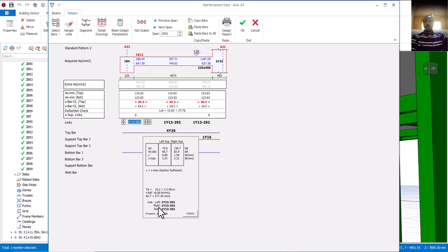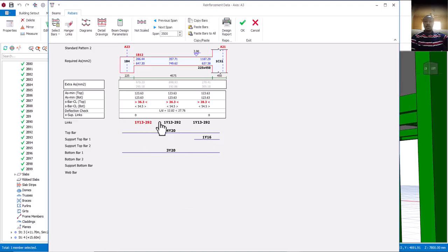So if this one has passed, at times why you see that red is because of this place. Understand? And this place talks about torsion. Many times why we see your link failing is because of this torsion value, and many times it is due to the excess check by the software. If you do it manually, it will definitely pass, more than even pass. So looking at all of these, we can actually ignore this particular red.